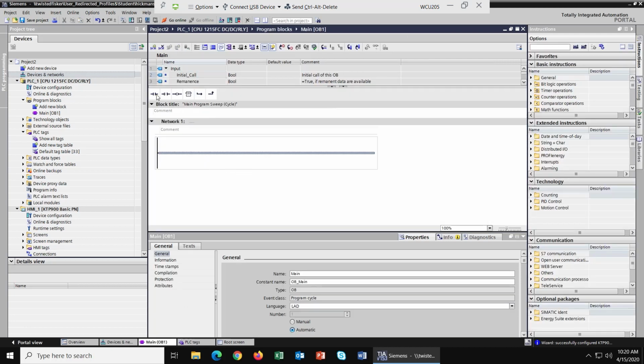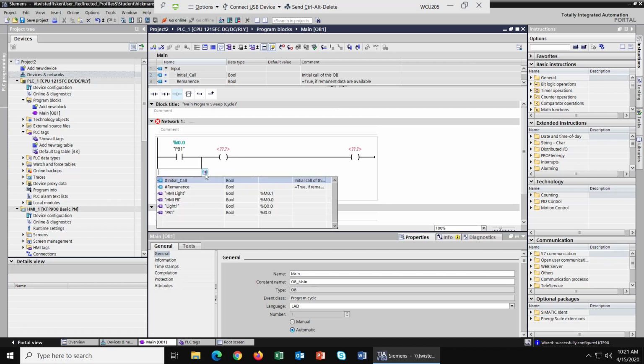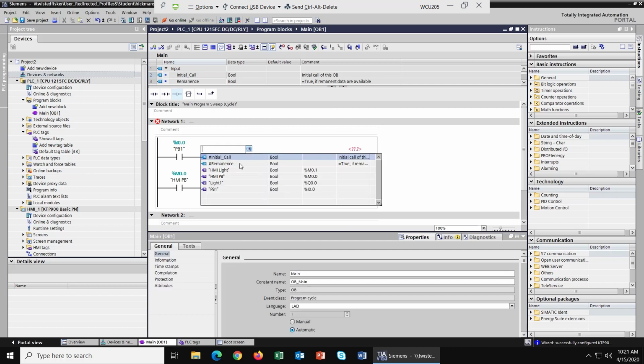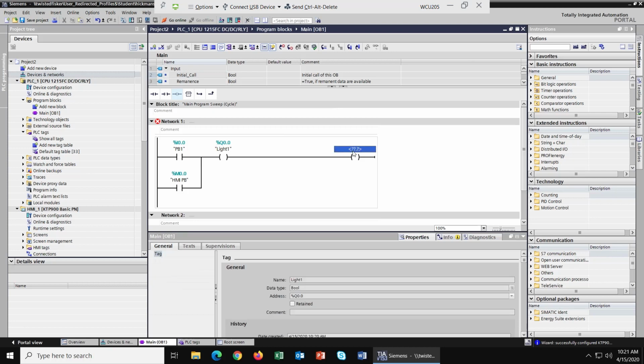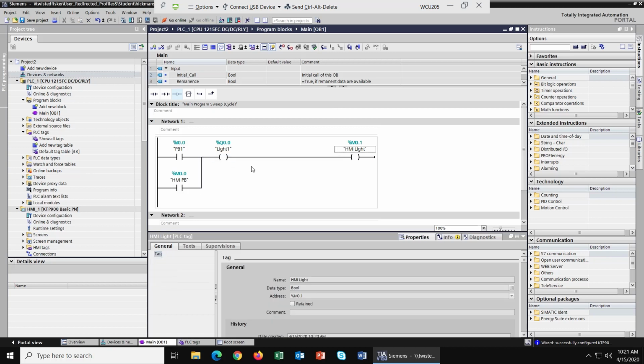and I'll program into the main right here. I'm going to put an OR here and another input, and I'll create that there, and I'll go ahead and do 2 outputs. So I'm going to have my real push button supposedly, or my HMI push button, which isn't real, it's on the screen, turn on a real light, or turn on the fictional light, the HMI light. Okay, so there you go. There's my ladder logic right there.